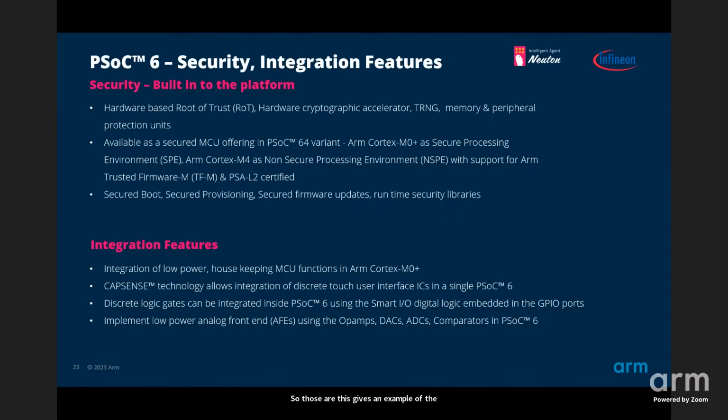And obviously, for the kind of demo that was shown today, a single chip solution is preferred considering the form factor, and it needs to be low power and at the same time secure, with all the recent security trends on IoT products. So from that aspect, security is built into our platform. There is a ROM-based root of trust that ensures that only authenticated signed firmware images could be run, starting from the boot code that is immutable since that is in ROM, and if it has been tampered with by any mechanism, the integrity of that code is invalid, and further code execution would not happen, for example.